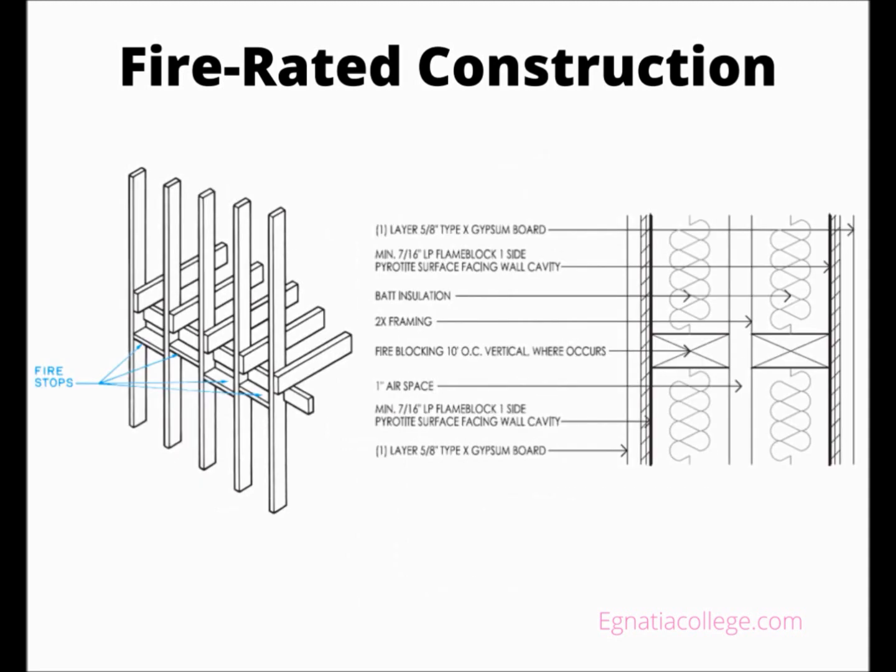Fire-rated walls must also prevent fire from spreading vertically inside the wall. If left open, the spaces between the studs in a frame wall act like chimneys, allowing flame to spread very quickly from one level to another. To prevent vertical flame spread, stud spaces are not permitted to be more than 10 feet high. The spaces between the studs are closed off with fire stops at each level. Instead of wood fire stops, the wall cavity can be blocked off with fire-resistant fiberglass insulation.